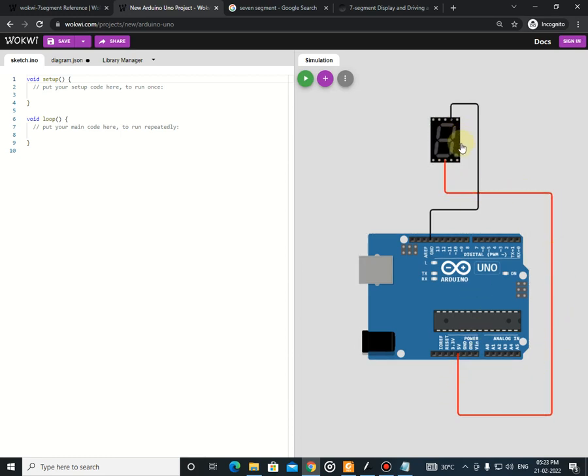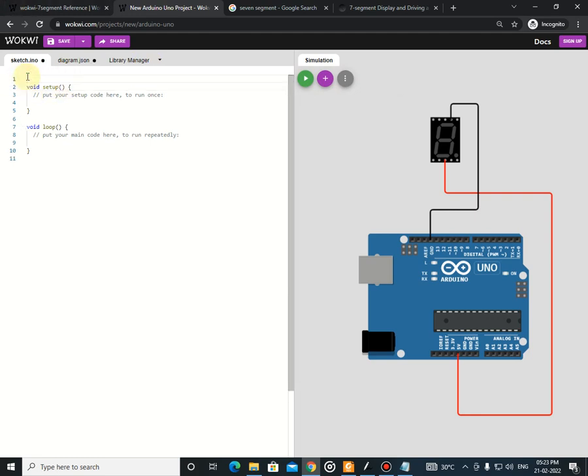All the LED anodes are connected to 5 volts. If it is a common anode connection, then it should work. So here you can see this line glows. That means it is a common anode connection. So now we are going to write a program to display on a 7 segment with the help of Arduino Uno without using libraries. It is similar to the earlier videos, where we interfaced 8 LEDs.